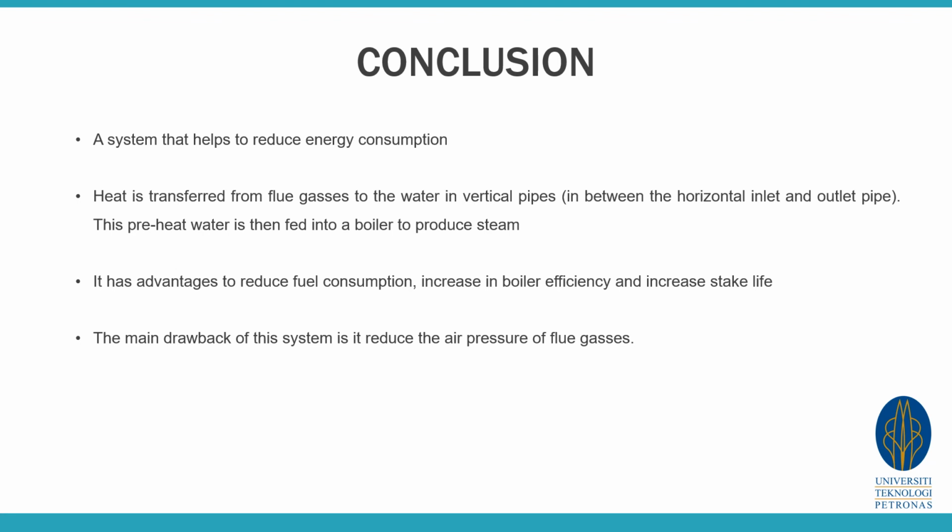The advantages of the economizer are reduced fuel consumption, increased boiler efficiency, and increased boiler life. The only major drawback of this economizer is that it reduces the pressure of the flue gases, which causes drag losses.